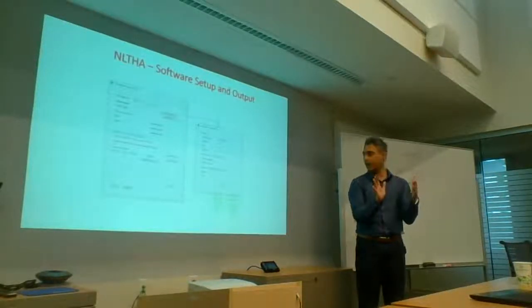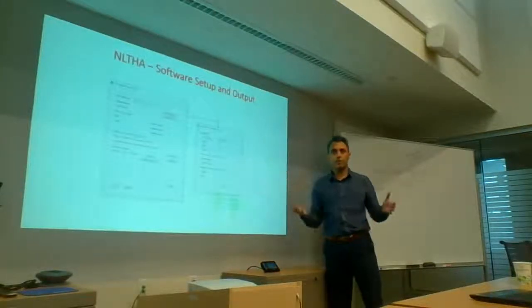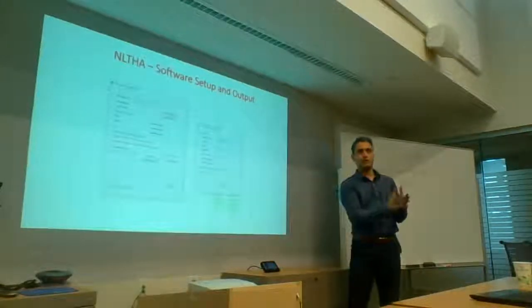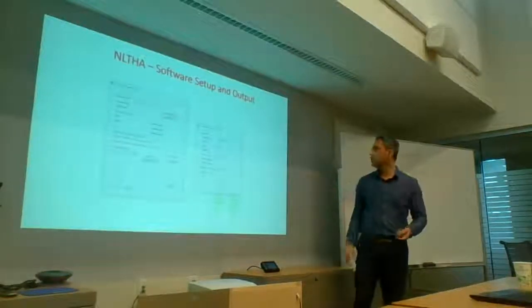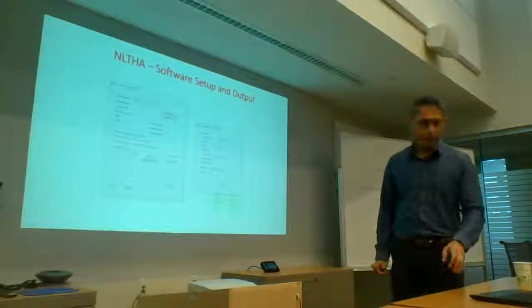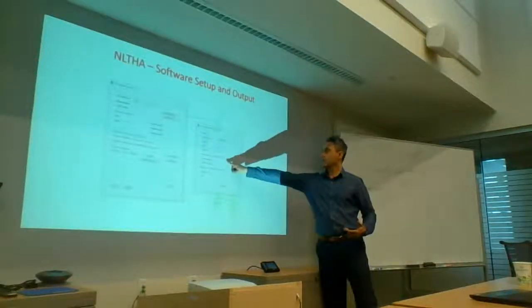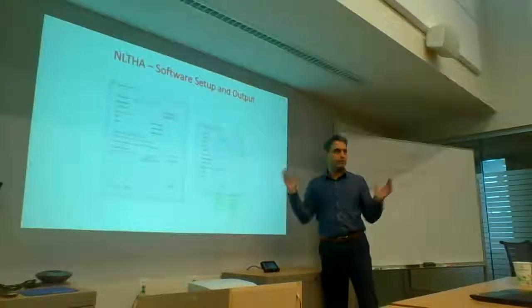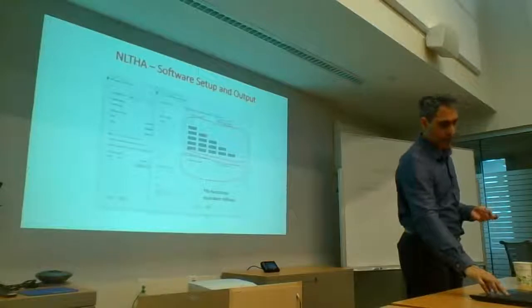So if you have a 25 mil gap, you just put that stiffness, and then you say, my opening is 25 mil. So for the first 25 mils, it's going to have no stiffness active. And then it's going to start to bring that stiffness into it. When you're running a linear analysis, then you need to put some value there. But then that's the only value it's going to work with. It doesn't have the ability to do anything else.